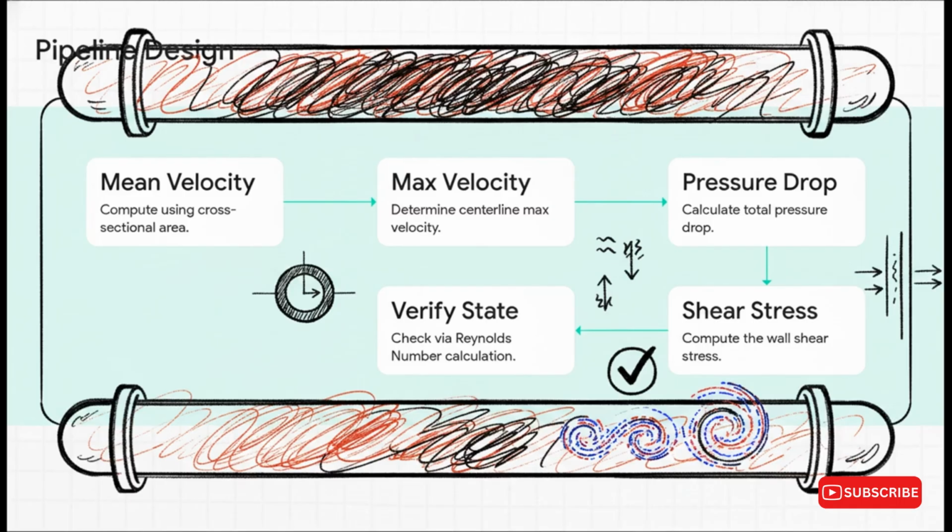But crucially, in step 5, they verify their assumptions by computing that Reynolds number. If they calculate a number around 600, well, that's way below the 2300 threshold. The viscous dampening is stronger than the chaos, proving their laminar design is perfectly safe to build.